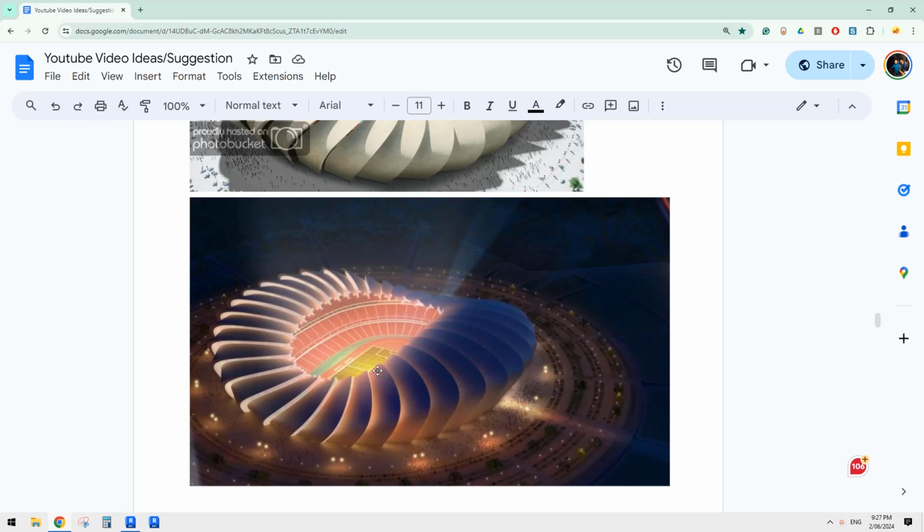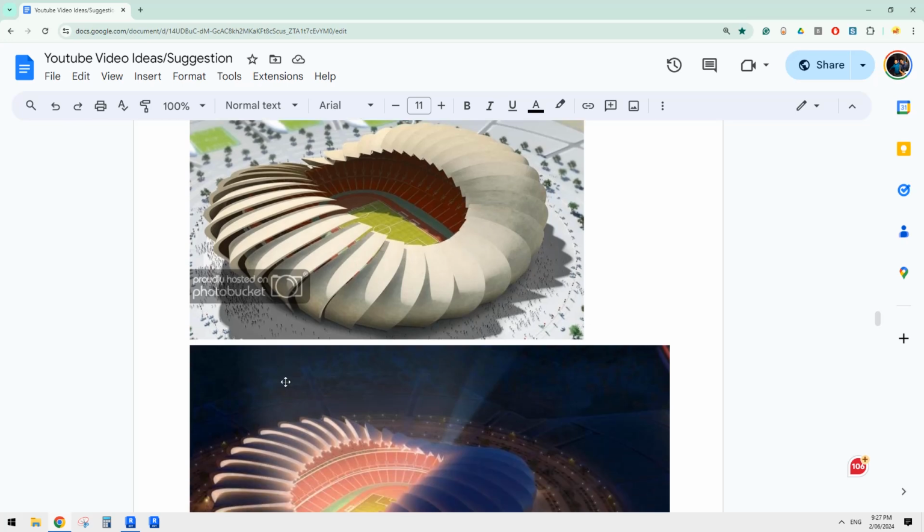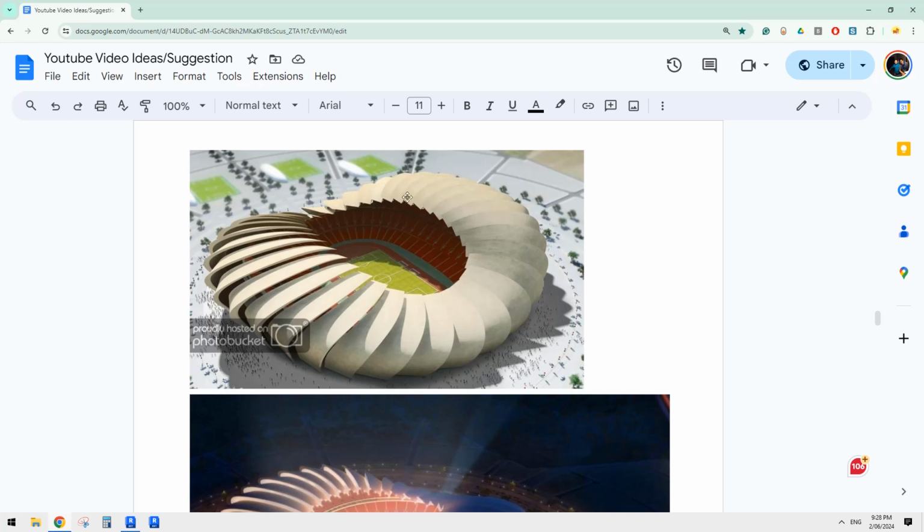Okay, so when we look at this one, we can create a surface and then use divided surface and then use a pattern-based family to create all these individual panels. The hardest part for this one is actually how we can create this as a single element, because we